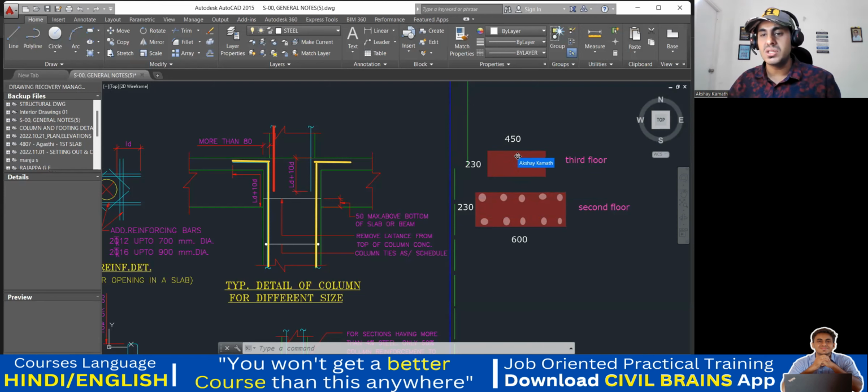So if there is a reduction in the size, now two things will happen. First, try to understand, I'll club both of the clauses we saw now. See this particular rebar, this rebar, this bar, and this bar is not required. Why? Because these four bars are not required, because my column size is only 450. This is somewhere here, so I don't require this bar.